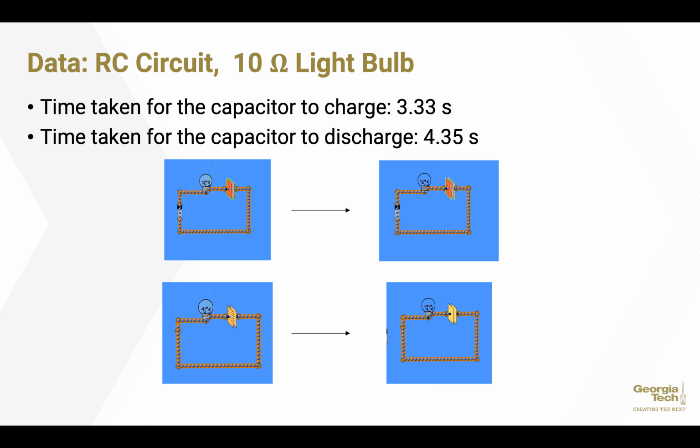For this next part of the experiment, we set up a circuit with one 9-volt battery, one light bulb, and one 0.2 Farad capacitor in series, and we timed how long it took to charge and discharge the capacitor. First, we set up the circuit such that it was powered by a battery, and the light from the light bulb slowly became dimmer as the capacitor charged. Then, we disconnected the battery and used the capacitor as a power source. Again, the light became dimmer as the capacitor discharged.